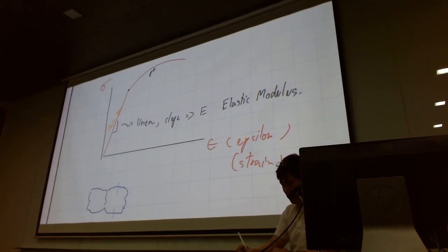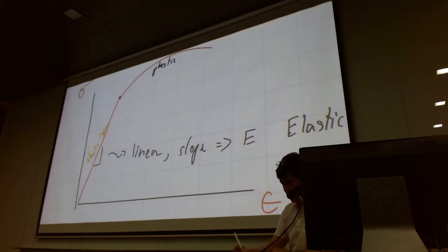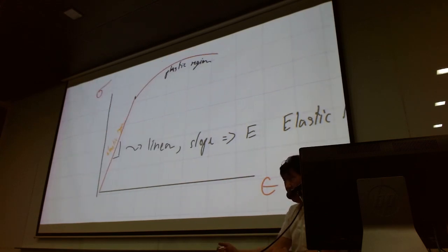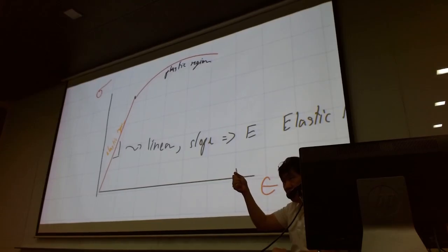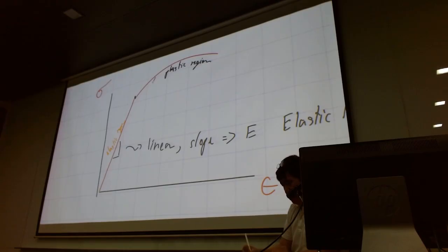So this is what we call a plastic region. Permanent deformation means what? It means that when you remove the load from the machine, the curve will go back down, but it will come back down in parallel to the original curve, to the original elastic line. This would be the same curve, same E. This is true for all metal.